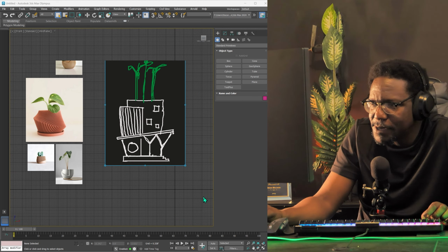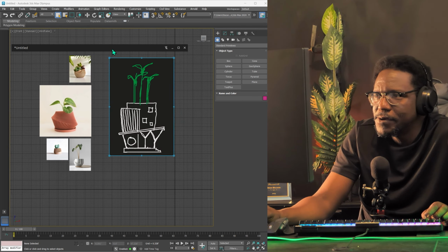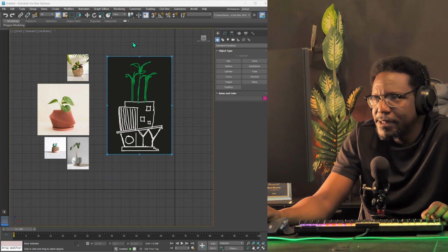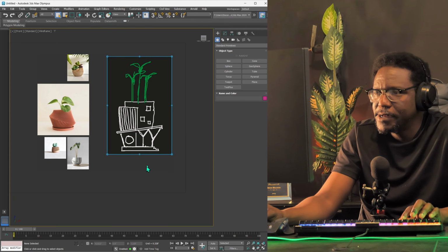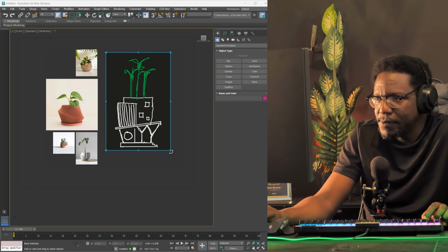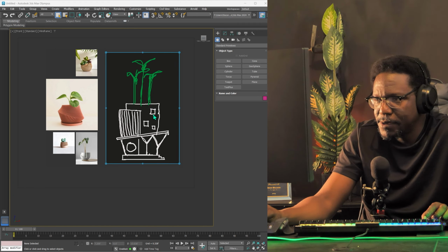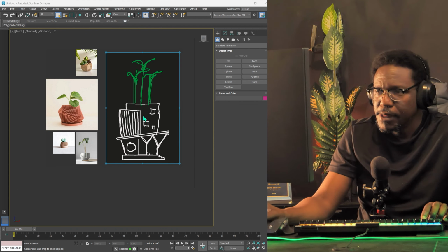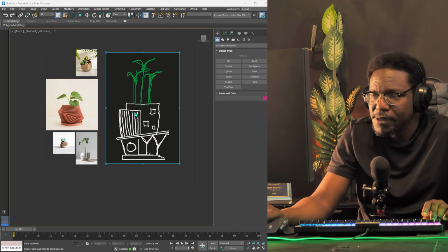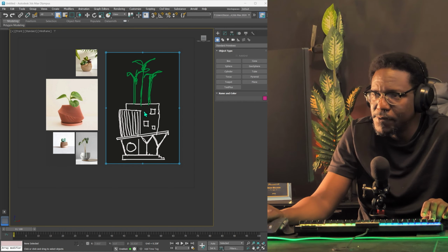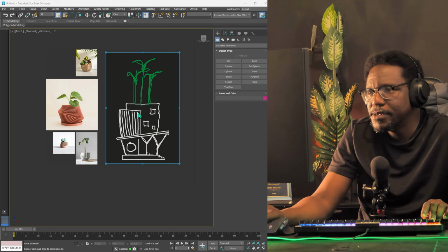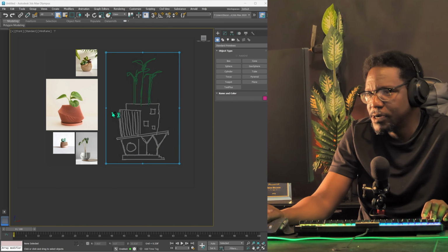Now it's a little tricky because I can't see where the window begins. Like you can kind of see the little edge there. If I turn off grid in Max there, you can see where the grid is. Now, what I'm going to do is leave this like that pretty much. Then I'm going to hold Control Alt Shift and left click and hold and move the mouse from left to right. Now this way I can set the transparency